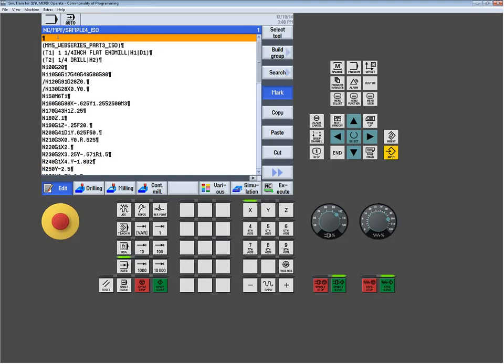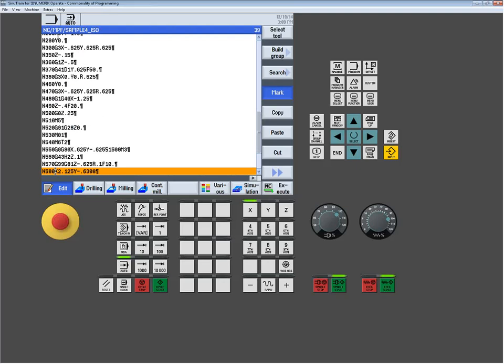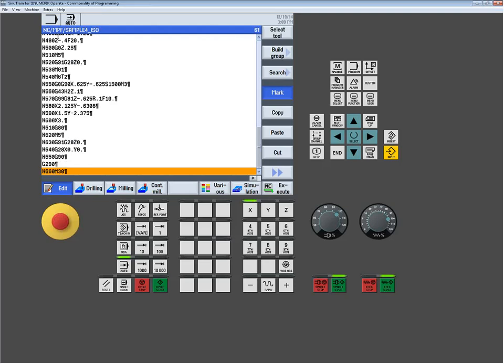And just prior to whatever I'm doing, I want to type G291. That's going to trigger ISO mode. Now, to get back into the Siemens mode, it's a G290. You don't have to do it at the end, but I usually teach guys to get in the habit of it. Most builders will automatically reinitiate G290 at the end of an M30, but you're still assuming that based on how the builder built the machine. If you put a G290, you're certainly not going to hurt yourself. This way you know it's switching back to Siemens protocol. So G290 is Siemens, G291 is ISO.